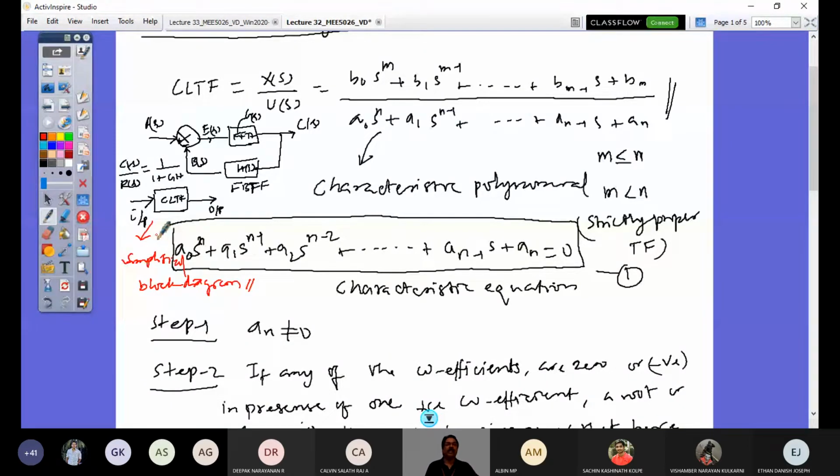So please have an idea that open loop system design is separate and closed loop system design is separate. In an open loop system the output is not going to get corrected. It would just give whatever is the nature of your system. For any input, there is an output. There is no need for a good correlation between output and input in open loop design. Whereas in a closed loop system, I want a good correlation of my output to the input. So I would take the feedback, do correction, and improve the transfer nature of my system so that I have a good correlation of output to input. So this is what we are going to look at in today's class.